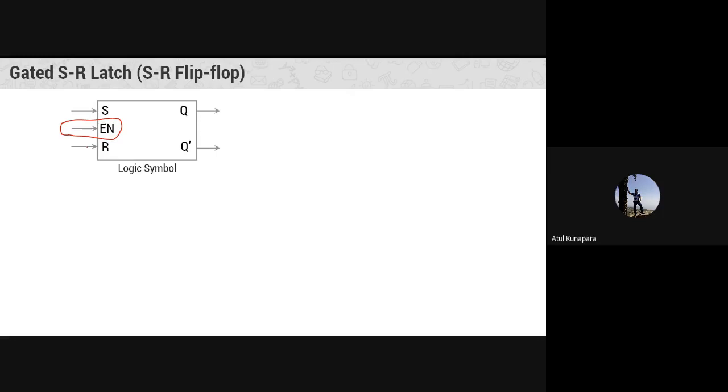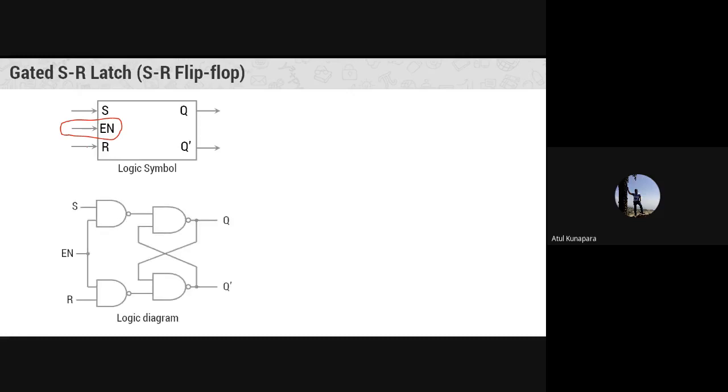Means that the enable signal is put at logic high, right? That is the only difference here. You look at the internal circuit here using the NAND gate. So the NAND gate logic circuit is here. See, this much part was there already. This was the part for the NAND gate SR latch.